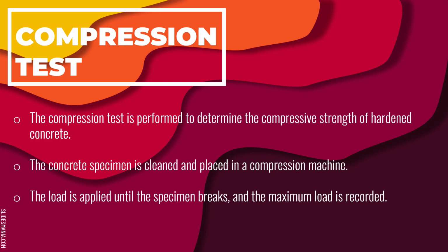The door of the machine was closed and the data of the specimen was filled in the software of the machine on the computer. The testing machine was started and the load was automatically applied by the machine until it breaks. The maximum load was recorded and the machine was cleaned.